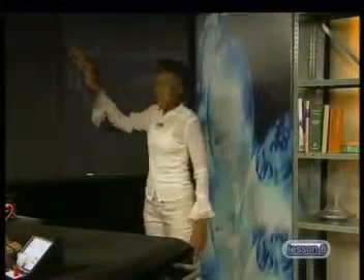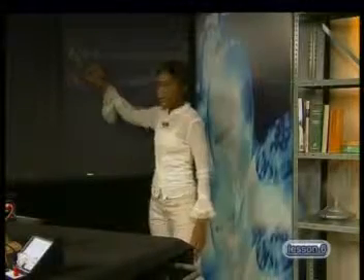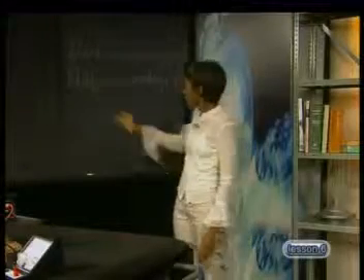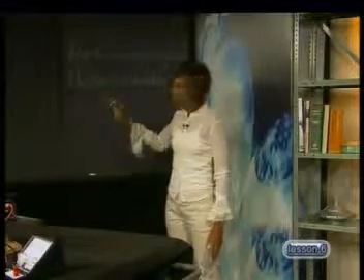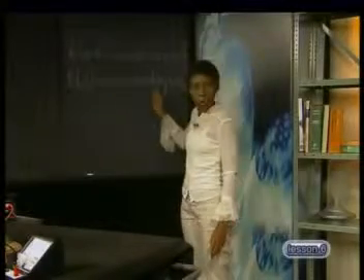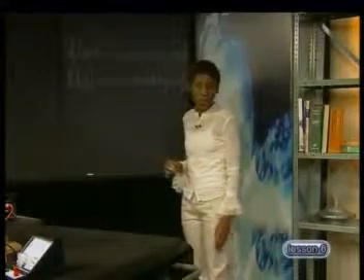Now, with this in mind, let's write an expression for the EMF induced in the secondary coil using Faraday's law. Here, we use the symbol V subscript S for the EMF in the secondary coil, and N subscript S for the number of turns or windings on the secondary coil.